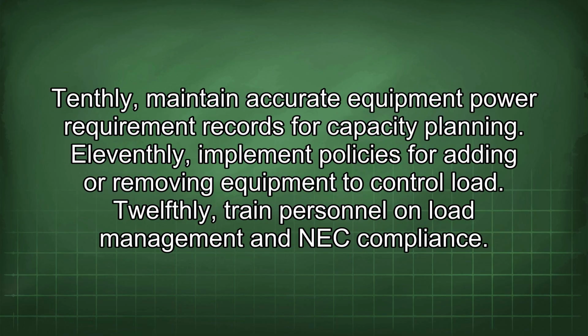Tenthly, maintain accurate equipment power requirement records for capacity planning. 11thly, implement policies for adding or removing equipment to control load. 12thly, train personnel on load management and NEC compliance.